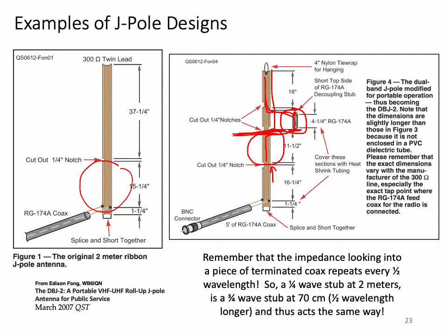So since the 70 centimeter antenna now is a true half wave end-fed, it has an antenna pattern with a lobe that faces the horizon exactly as we wanted. And the same thing is true for 2 meters. So this antenna works properly in terms of its radiation pattern for both 2 meters and 432.